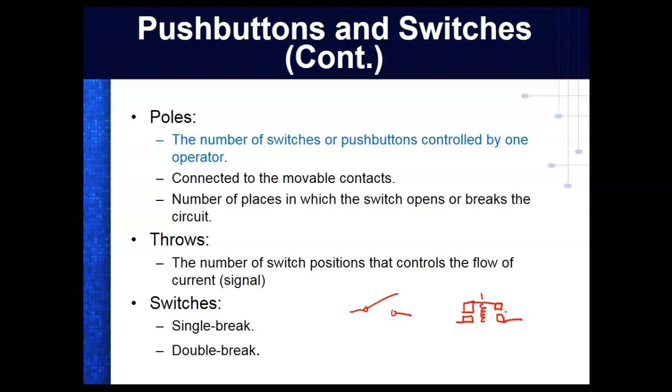So if one side gets welded together, it'll tilt up and break away. When you got something that you're trying to break loose, you usually tilt it up, right? You understand? So it has a better chance of breaking the weld away. So yeah, just about all, not all. Those are the contacts. The push button, double break contact.